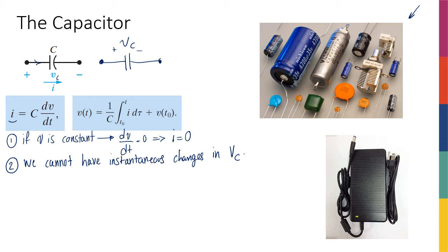I've shown this picture here because if you have a charger, especially an older one, you might have seen this kind of LED on the charger that is an indicator of whether the charger is connected to electricity or not. When you unplug the charger from the wall outlet, you might have noticed that this LED doesn't turn off immediately. Depending on how much capacitance you have in there, it might take a few milliseconds, a fraction of a second, or in some cases I've seen 1 or 2 seconds. It just fades away. The light goes down and then becomes off after a few moments.